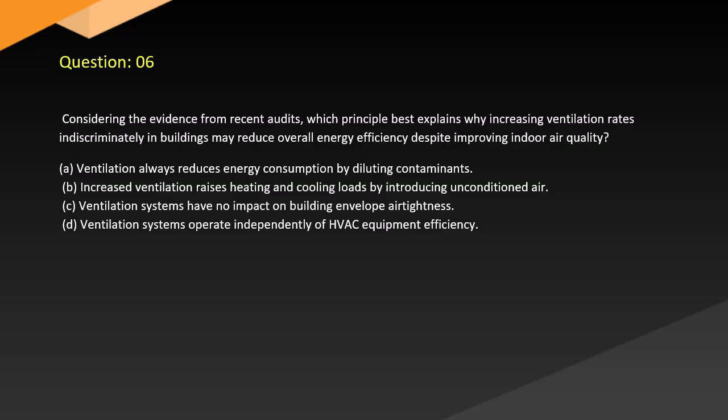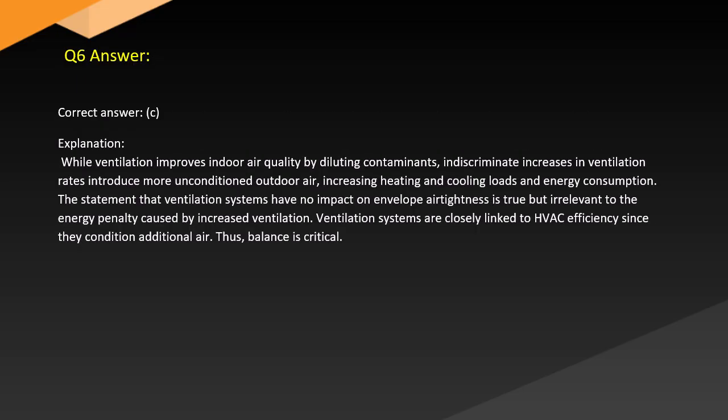C. Ventilation systems have no impact on building envelope airtightness. D. Ventilation systems operate independently of HVAC equipment efficiency. Answer. Correct answer. C. Explanation. While ventilation improves indoor air quality by diluting contaminants, indiscriminate increases in ventilation rates introduce more unconditioned outdoor air, increasing heating and cooling loads and energy consumption.